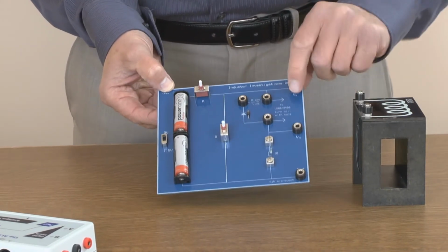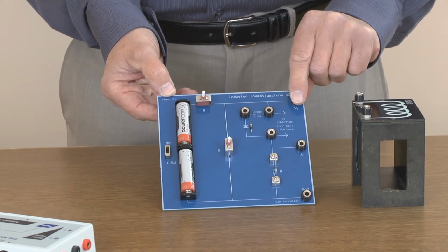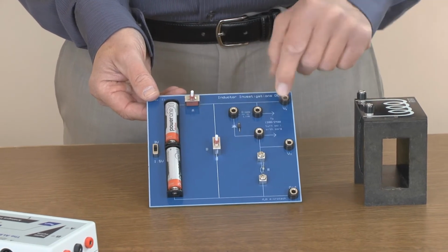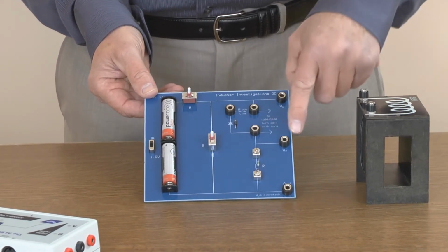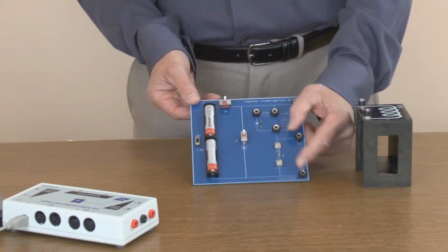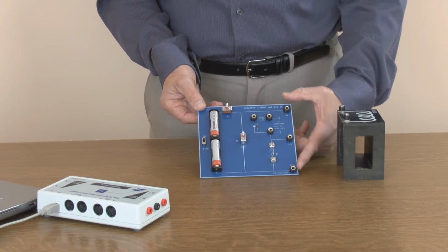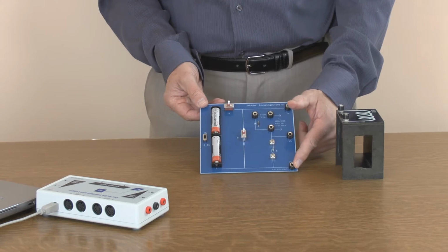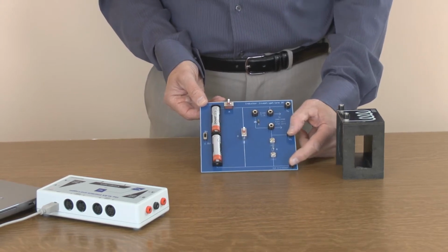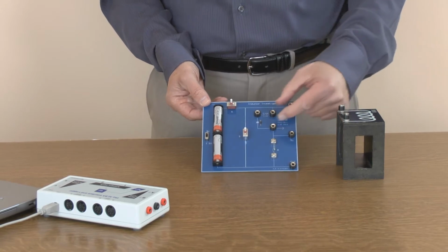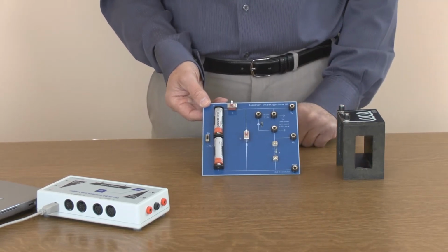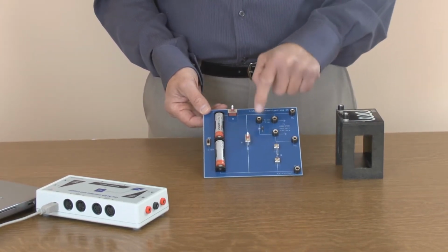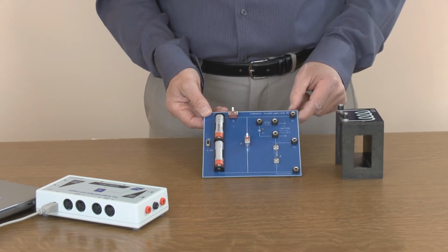I have three terminals here which will connect to our Alba data logger. The top one here gives positive voltage. This is a ground, and the voltage between here and ground gives us the voltage across the resistor. Between the top and ground gives us the voltage right across the two cells. If I subtract the voltage across the resistor from this one, I am left with the voltage across the inductor. We're not using this switch just now. The diode is in to protect the interface from any spikes.